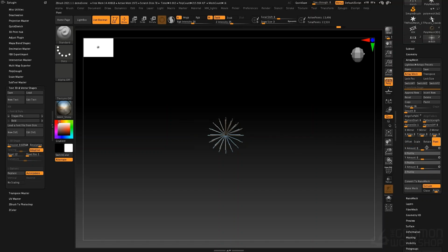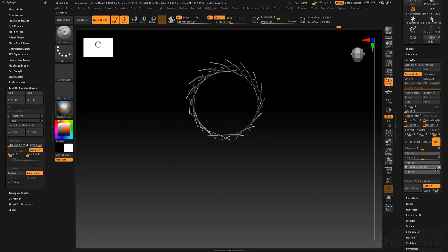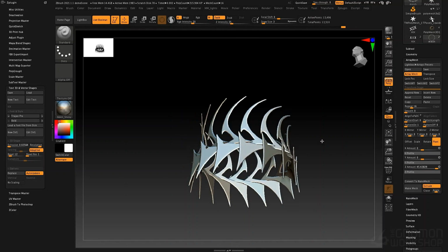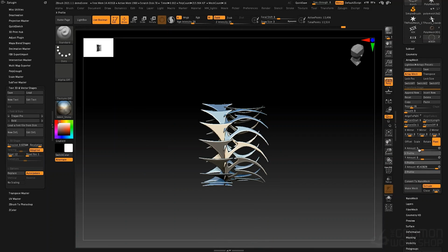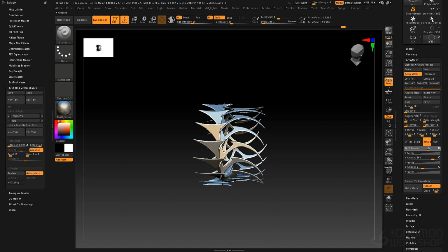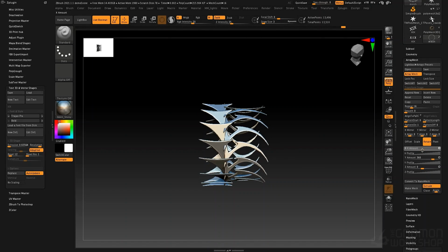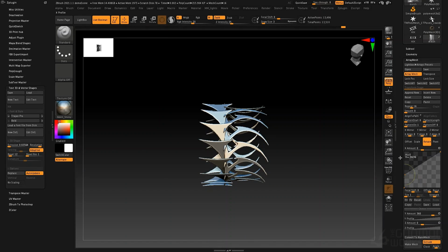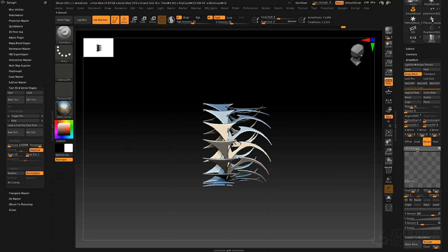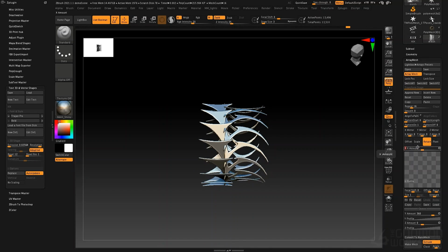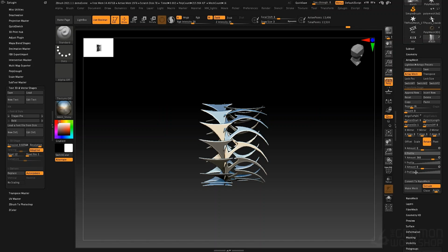If I offset it in X, you see how that actually changes the geometry that's created. Or if I go to my pivot and then change the pivot in the z-axis, we get something like this. You see that we can make all sorts of really cool shapes by repeating this in instances. Maybe I want to rotate this around the x-axis. I go to rotate, and if I rotate it around the x-axis, I can get something like this. If I want that rotation to be completely the same all the way through, I'll just flatten that curve, and I can rotate it like this. We'll set that back to 0. Close that curve by clicking close here.